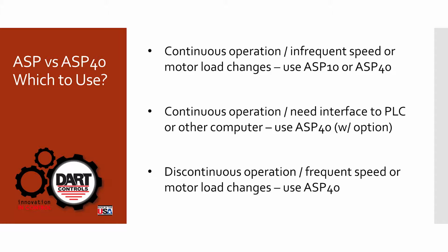If you have a continuous operation but you need to interface the ASP to a PLC or some other type of computer, in other words, you want to be able to adjust the set point on the ASP automatically, you need to use an ASP40 with the appropriate option.